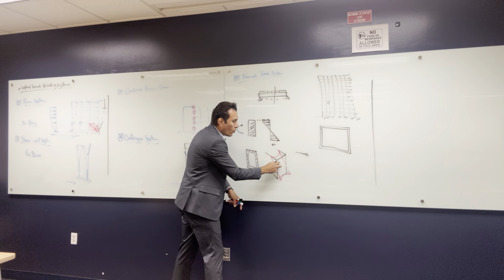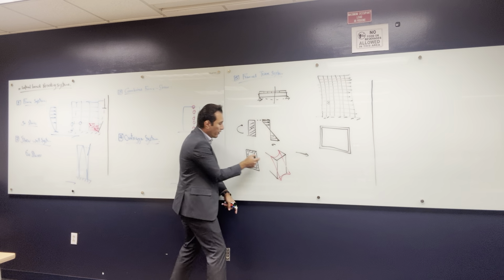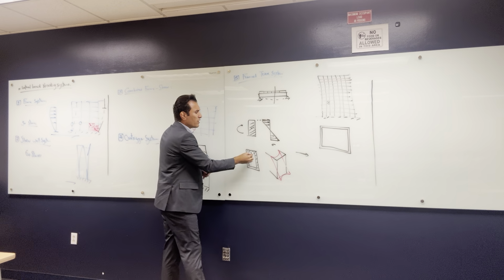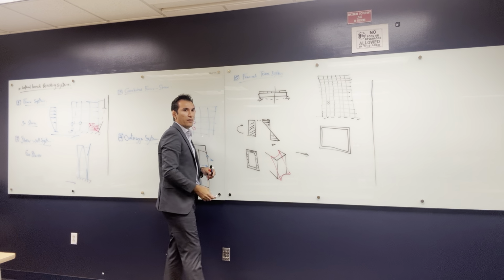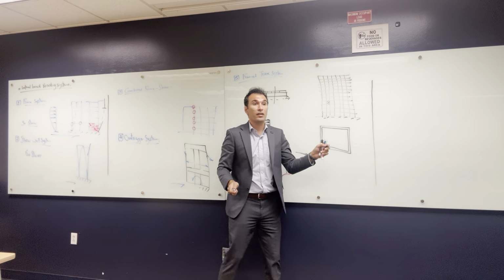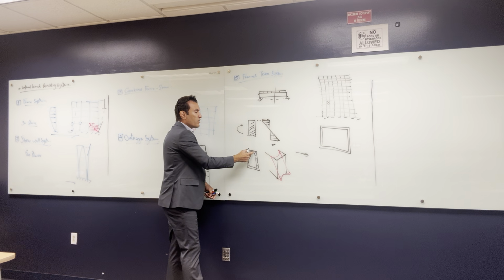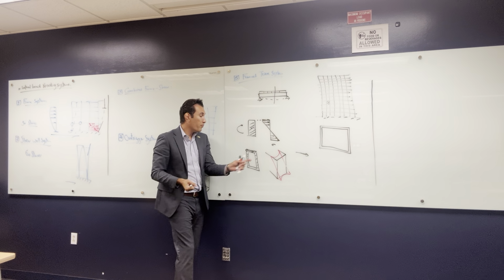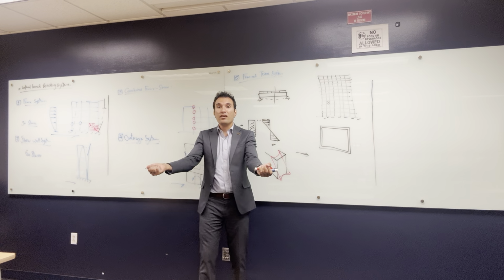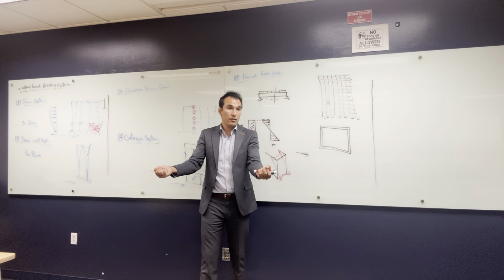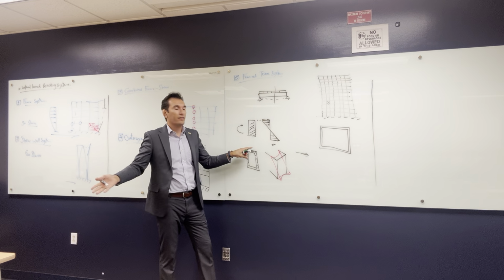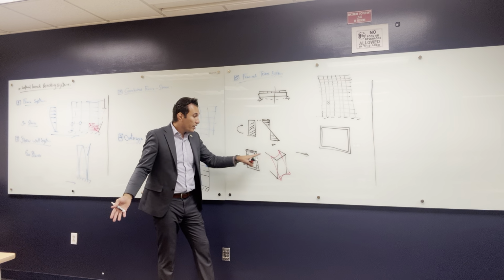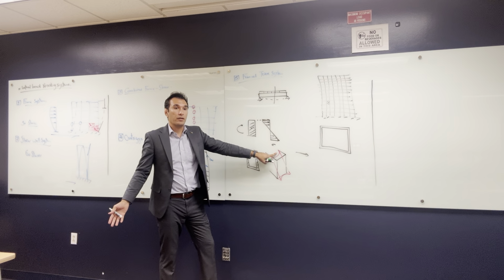But the stiffer it gets, like if this part is very stiff, let's say we increase the stiffness of this part, make it very, very stiff, increase the material, make the stiffness infinity. If the stiffness of this part is infinity, so if you are gonna pull this part up and pull this part up, we're not gonna leave this part. We either all go together or we stay together. So it depends on the stiffness of the flange, but definitely the flange stiffness is not the same as the other section. So what happens is a shear lag over there.